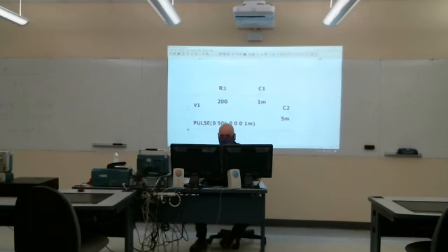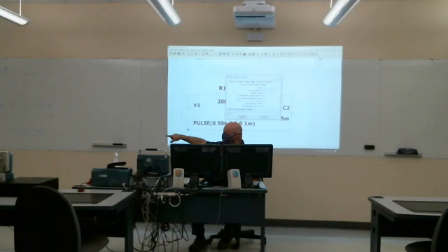Okay, so here we want to do what's called a transient analysis, and we start at 0, and then the time constant for this thing is 1/6 of a second, so it decays away, and about 5 time constants are about a second.